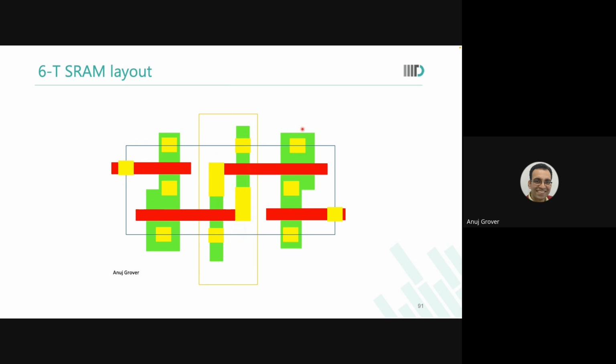The reason behind this is that if I were to make two contacts over here, one for the inner node of the PMOS and one for the gate of the PMOS, and make these two separate contacts and then connect them by metal, I will need to keep contact to contact spacing. That will make my cell taller.